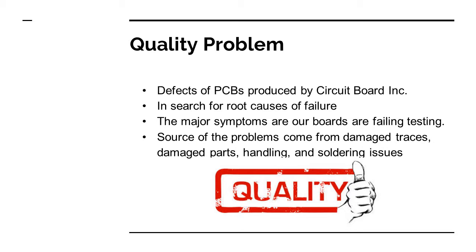In terms of our quality problem, we're looking at the defects of PCBs produced by Circuit Board Incorporated. We were in search of the root causes of failure for these PCBs. They were failing testing, and we were trying to find the symptoms behind it. The sources of the problems included damaged traces, damaged parts, handling, and soldering issues.